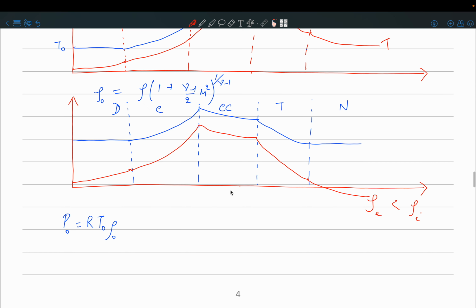Now the reason is that, see, we try to achieve this particular condition because in combustion we prefer that the molecular weight of the products is lesser than the molecular weight of the reactants. Now this is a very important point in rockets, not so important in turbo machineries, but it is something worth remembering. Okay. Is this clear? Should I move on?